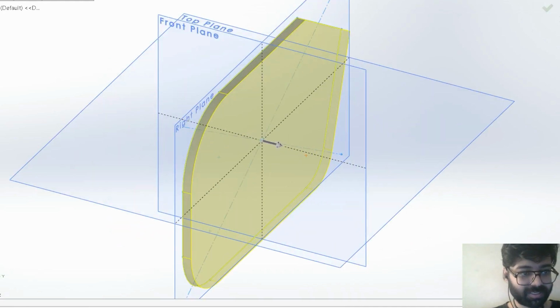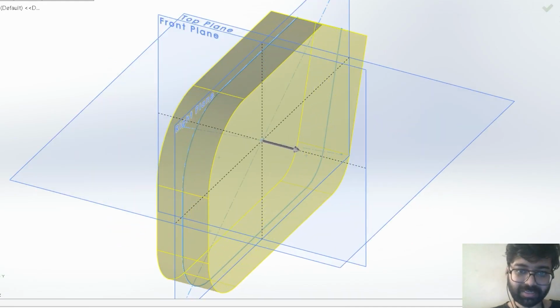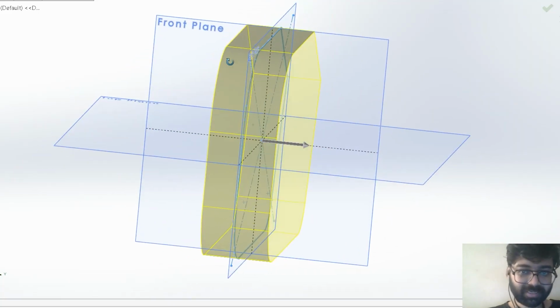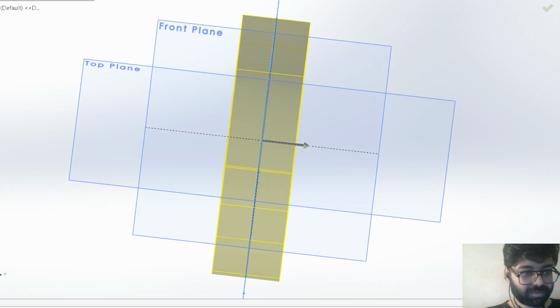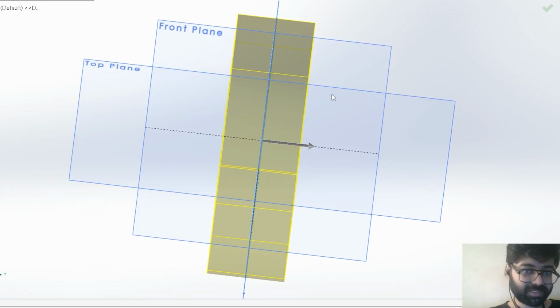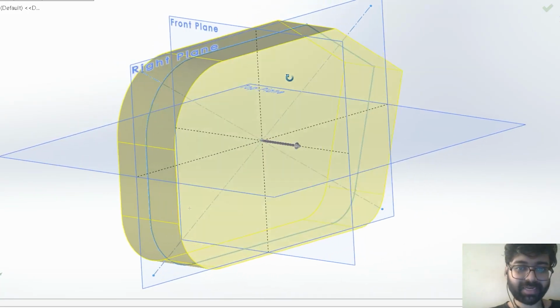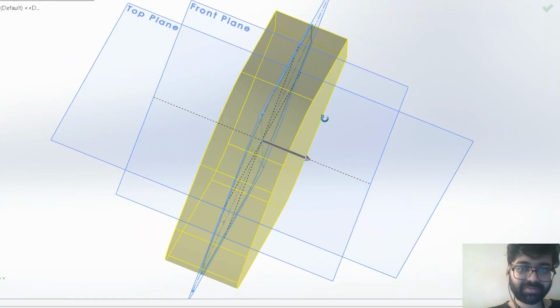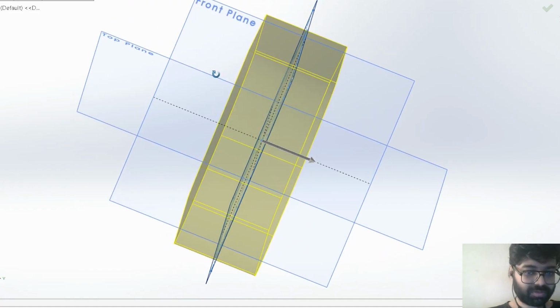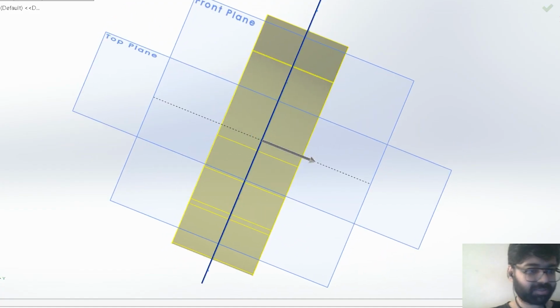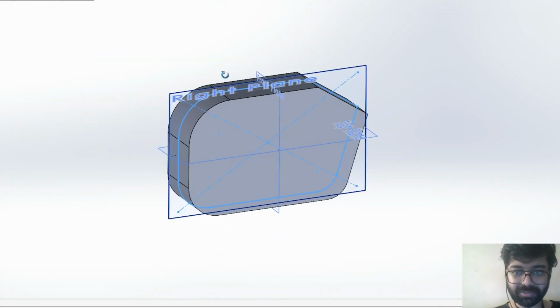I'll apply some material here, mid plane. So see, this is called extrusion in technical terms. Extrusion means you are adding material to a sketch. So whatever sketch I have done, I'm adding material here. I'll give a thickness a little bit larger so that later on we can cut out extra material if required. So I'll be giving around 90, suppose 90 mm thickness, 9 cm. Later on this also can be modified, so not an issue.